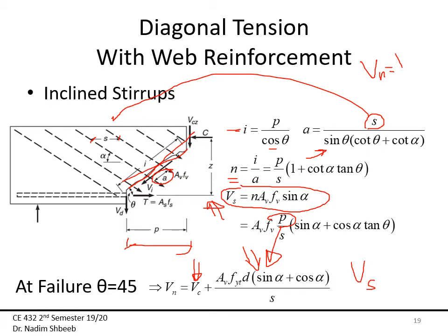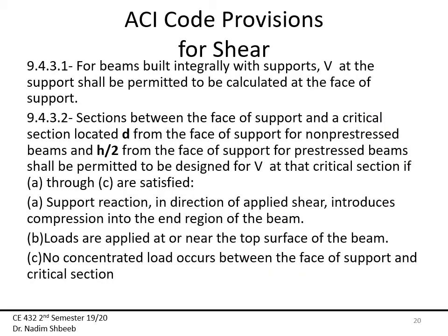So the strength, or what we're going to call the nominal strength of reinforced concrete, is simply the shear in concrete, which I'm going to call Vc, plus the shear in steel, or due to reinforcement. We will talk about this in the upcoming recordings, and we will tackle this now. But before we do, we have certain rules to adhere to.